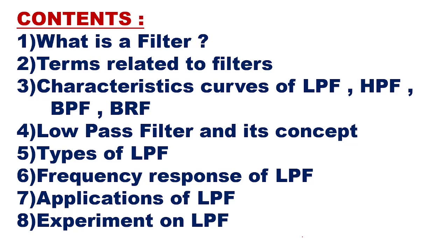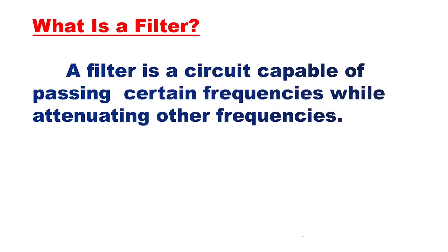Filters are used in our communication. So here we can see the definition of filter. A filter is a circuit which is capable of passing certain frequencies while attenuating or rejecting other frequencies. Now what does this mean?